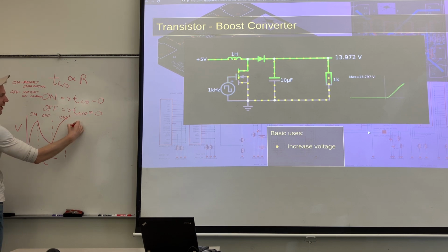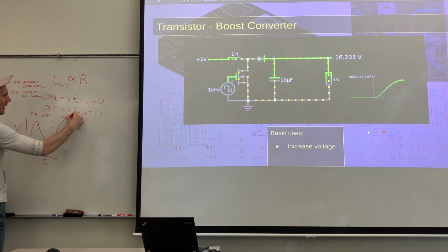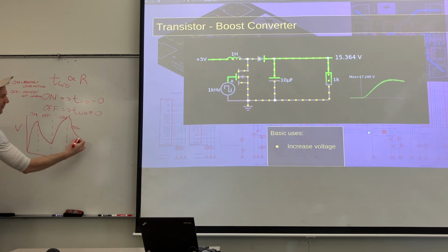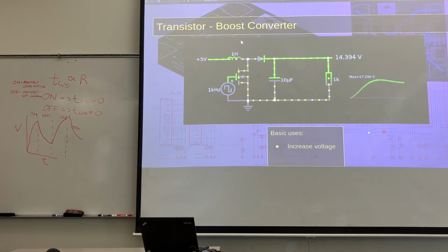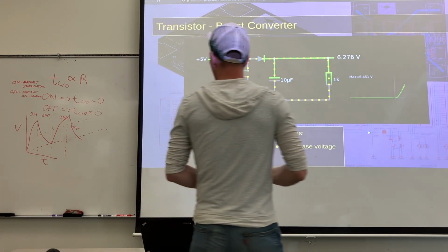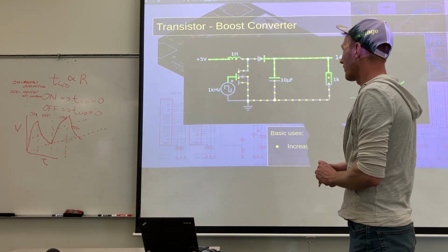And then when it goes back off, you continue to not fall to the lowest point. So you have this stacking cumulative effect where your lowest possible voltage is slowly going up, and your average voltage, which you can smooth further using capacitors and inductors with your load, in an ideal world, you can kind of smooth that out.